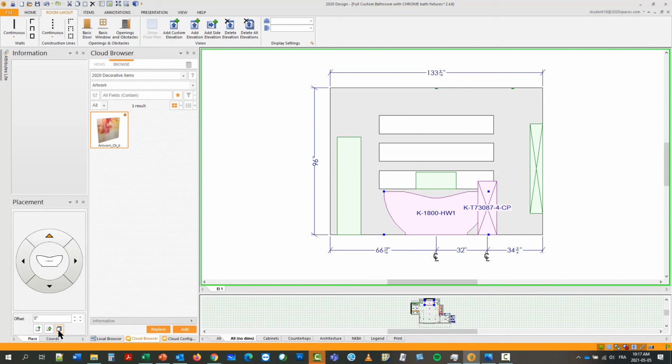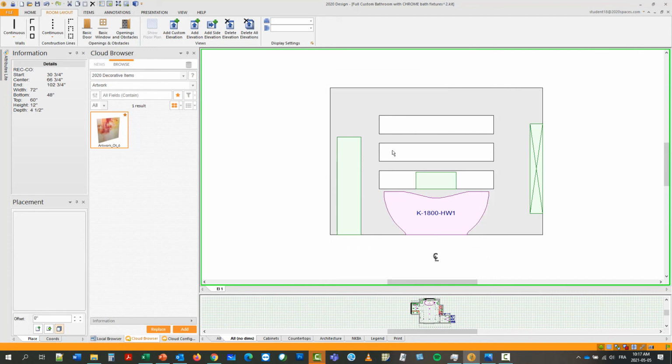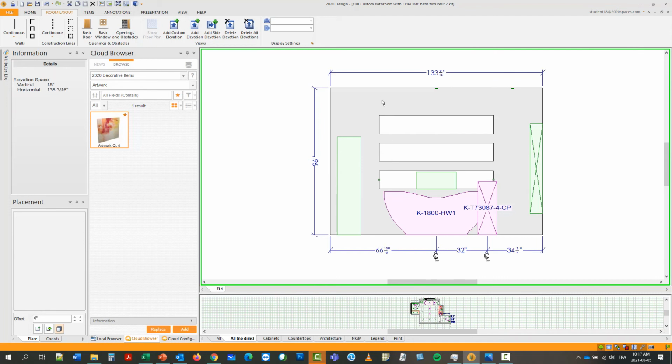So this is something that we can do, and that's the trick to get the spotlights exactly where you want it inside a room. That said, if I click on the cutout, you will see that I don't see it inside the placement. So this little guy is part of the same family as windows and doors. So unfortunately, I'm not able to use that technique to place these guys at the same distance. I can use copy paste, but I will still have to move it and adjust it to the proper height and placement.